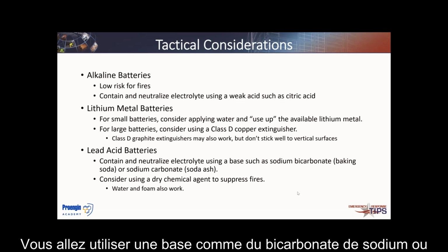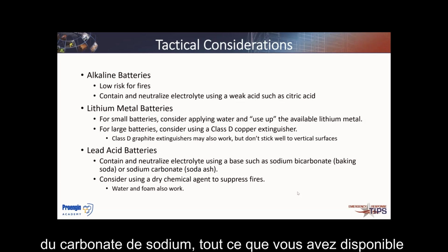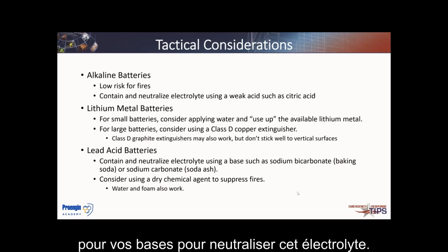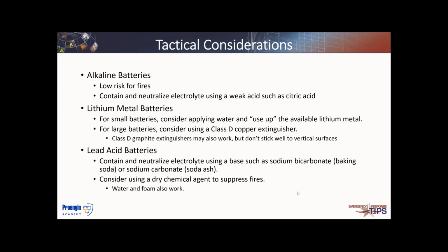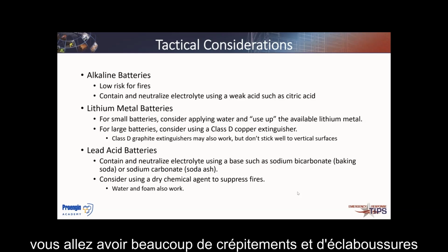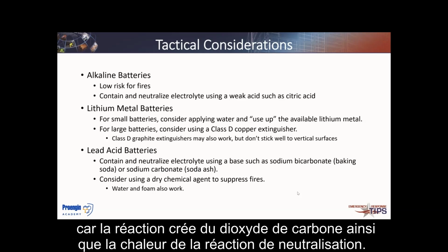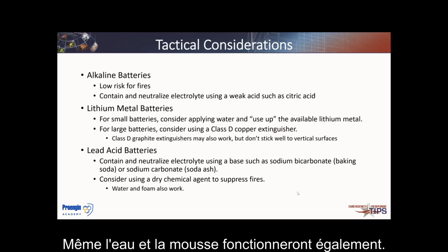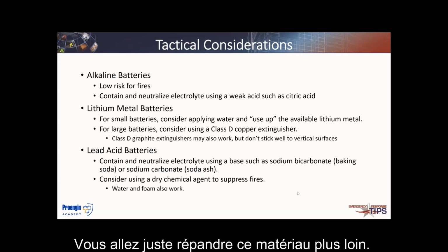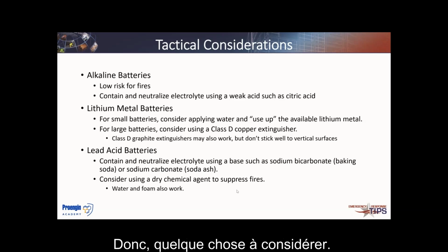So you're going to use a base like sodium bicarbonate or sodium carbonate, whatever you have available for your bases, to neutralize that electrolyte. Just remember that if you use the carbonates, you're going to have a lot of sputtering and splattering, as the reaction creates carbon dioxide, as well as the heat of the reaction from the neutralization. If there is a fire, consider using dry chemicals. Even water and foam will also work. You're just going to be spreading that material out further, and so something to consider.